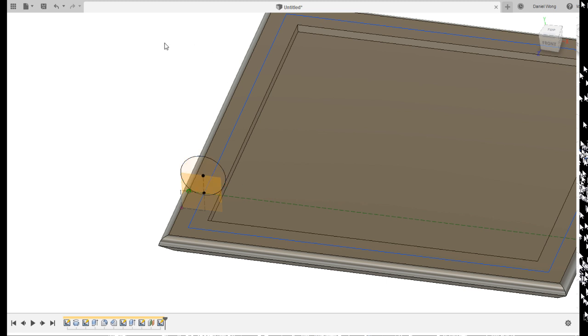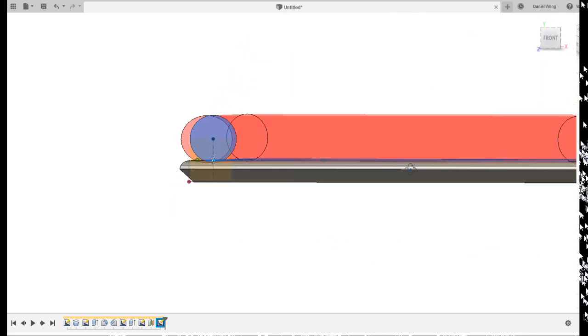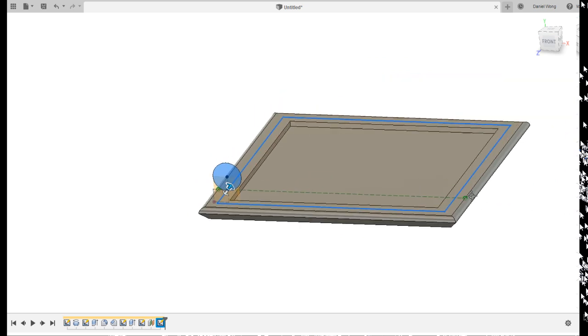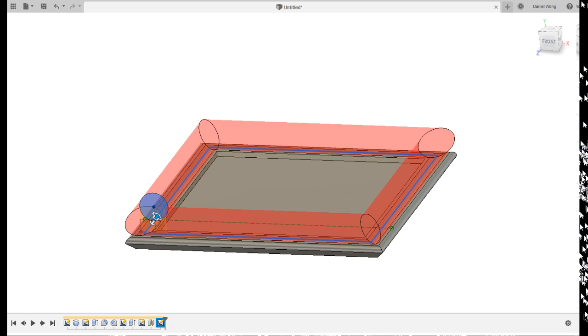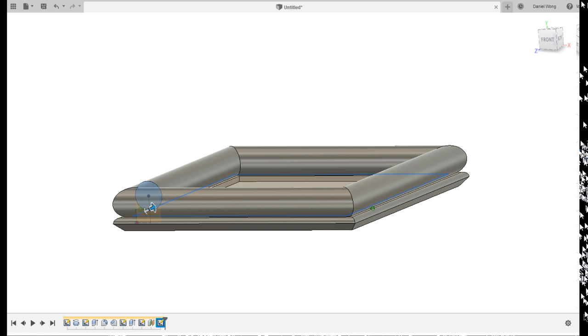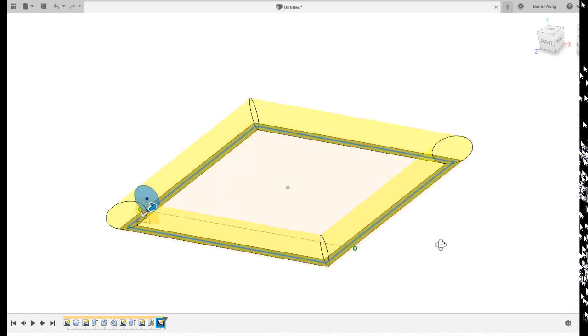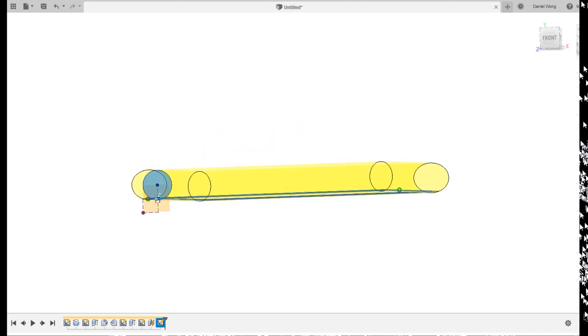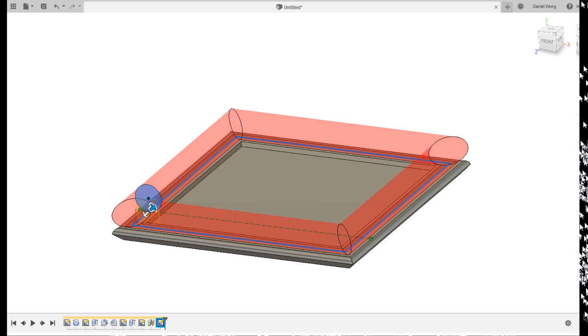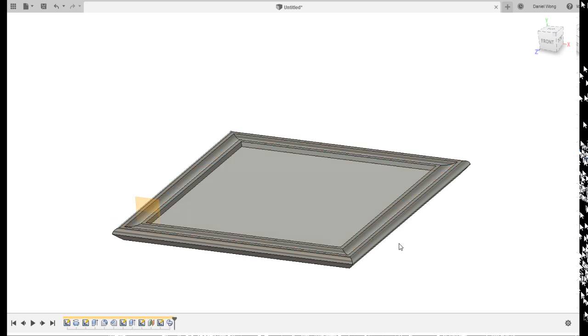So I'll go create and I'll go sweep. I'll select my shape in the profile and then I'll select the path that I want to trim around. And you'll notice that this happens, right? Because it's going to cut this rectangle out. Yeah? Obviously, again, you can go into operation, you can go join, and we'll have this sudden huge tube on there. Doesn't look pretty. We can do intersects, and we can just keep that little slither there, or we can do cuts. Okay, if I press OK, you'll notice that suddenly we have a little...